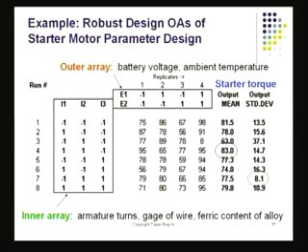We have a situation here. This is like starting your car early in the morning when your battery hopefully is fully charged, and of course the voltage of the fully charged battery, if it is used for a while, will be partially charged. In fact, that's going to reduce its voltage. Then of course I've got ambient temperature. You know very well, on cold days, when the temperature outside is cool, it's not very easy to get all the juice that you want from the battery. But the starter motor better crank. I better turn the full engine with all its might.